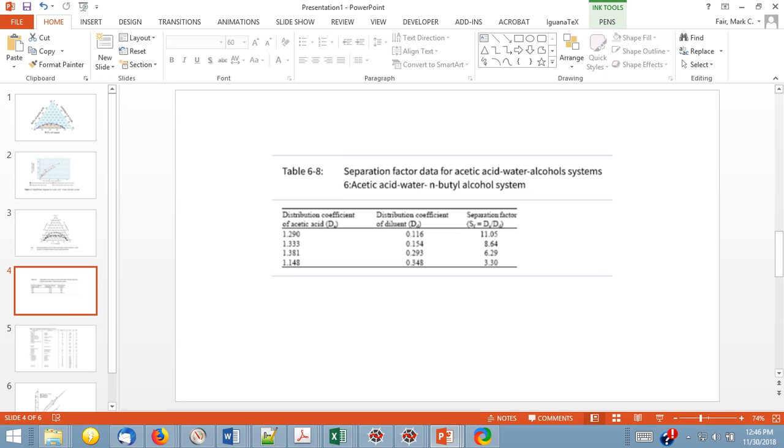So again, the point of all this is that getting the equilibrium data is a tough part of a lot of these problems. Once you know how to do the mass balances and energy balances, using things like Kremser's methods and McCabe-Thiele and all that, it really comes down to collecting appropriate thermodynamic data for these kinds of systems.